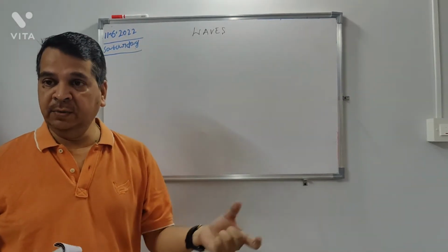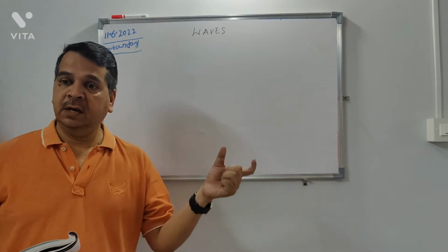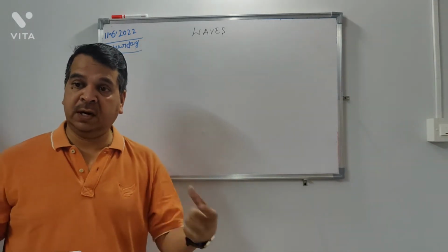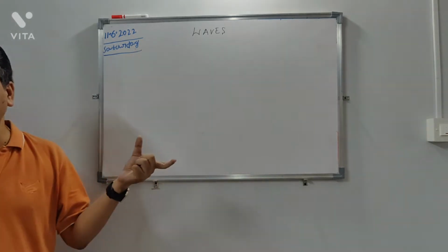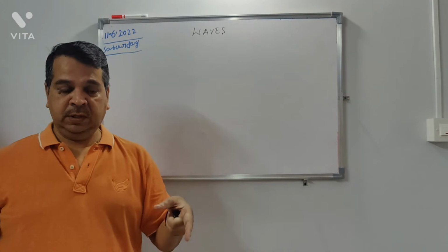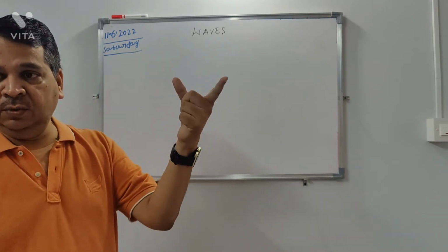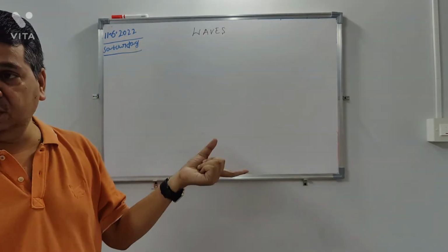When you are doing that, you have to spend work. As per nature's law, heat will flow from high temperature to low temperature. But if you are trying to transfer heat from low temperature to high temperature, you have to spend some work. So Q2 you have to take from the refrigerating chamber, and with the help of some compressor work, it will be thrown out to the surrounding.